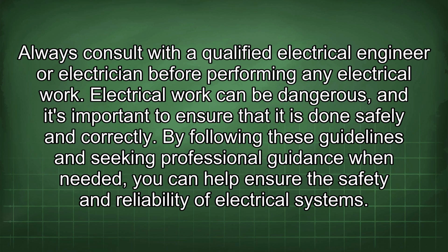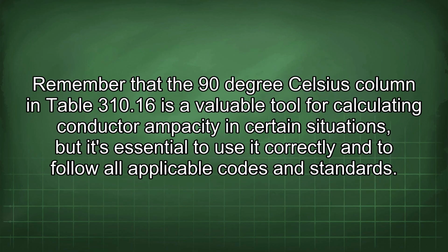By following these guidelines and seeking professional guidance when needed, you can help ensure the safety and reliability of electrical systems. Remember that the 90°C column in Table 310.16 is a valuable tool for calculating conductor ampacity in certain situations, but it's essential to use it correctly and to follow all applicable codes and standards.